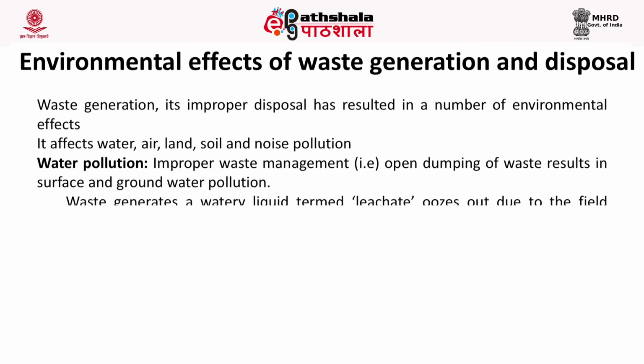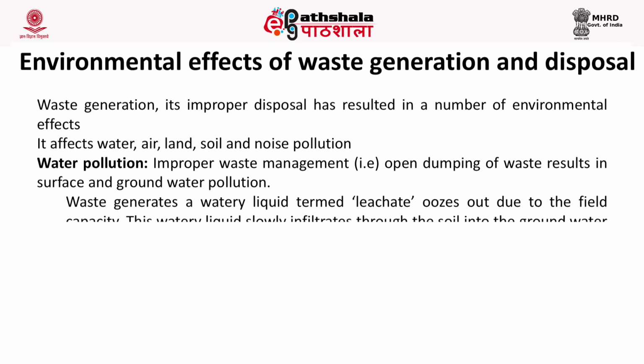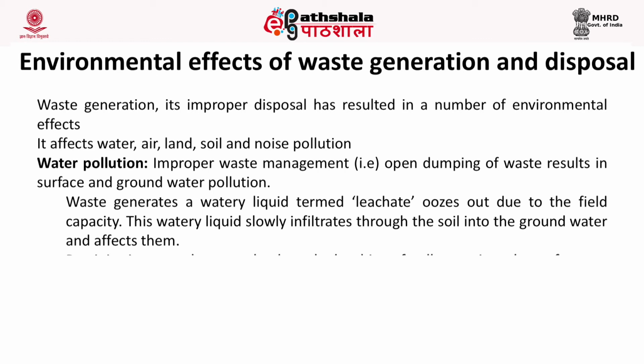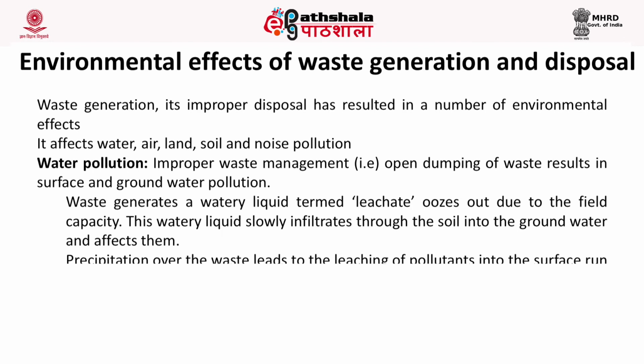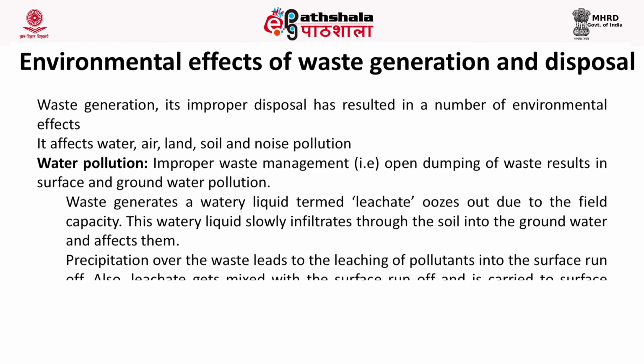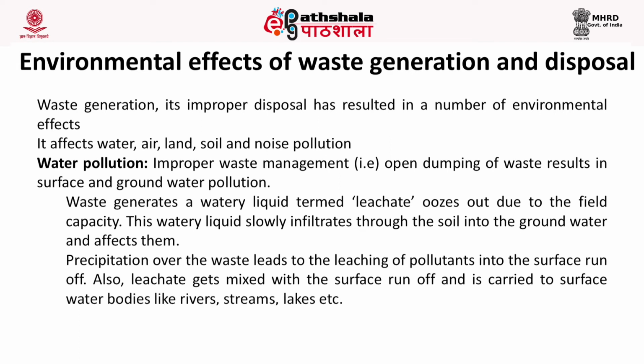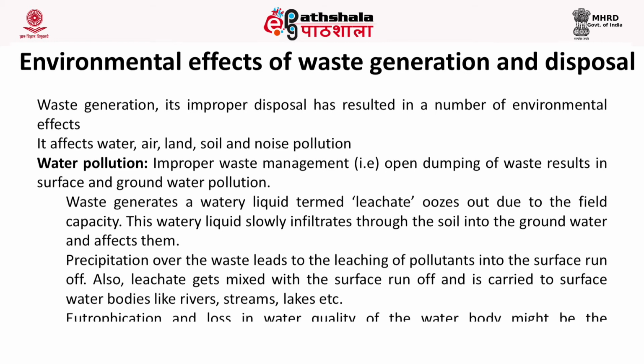Now, improper waste management, that is when you open dump the waste in an uncontrolled area, will result in disturbing or destroying your water quality, both your surface as well as your groundwater quality. You all know that the waste contains some amount of moisture, and when it starts degrading or decomposing, it releases a watery liquid which oozes out due to the field capacity, called your leachate. Now, this leachate, when it oozes out or flows, slowly infiltrates into the soil and slowly reaches the groundwater, thereby affecting the groundwater quality.